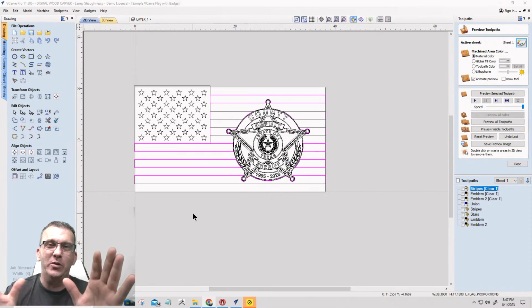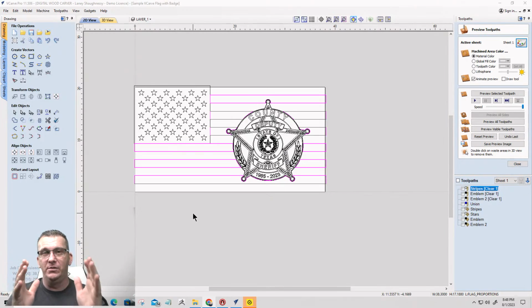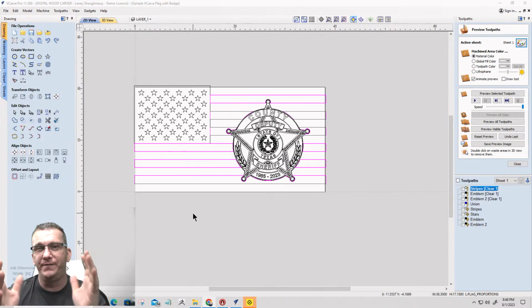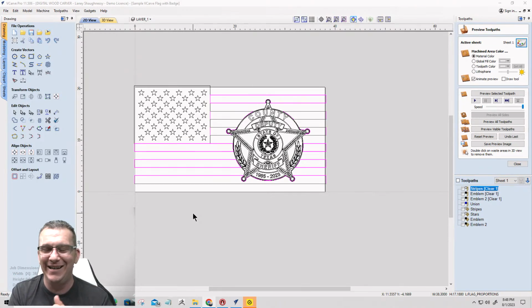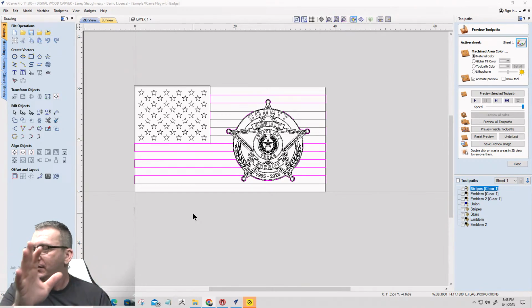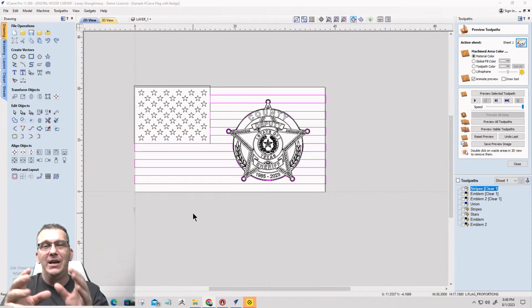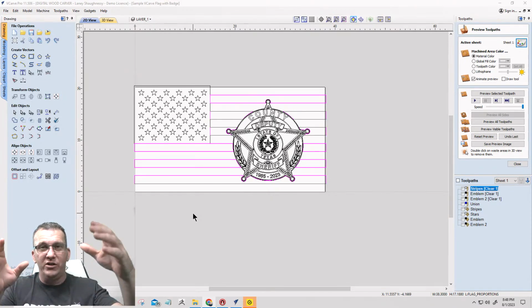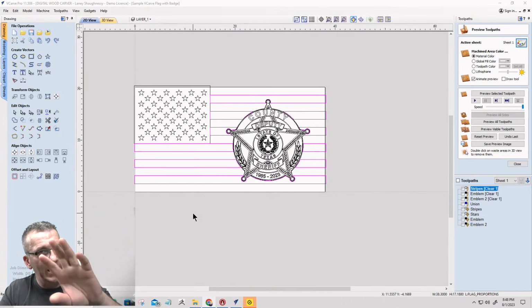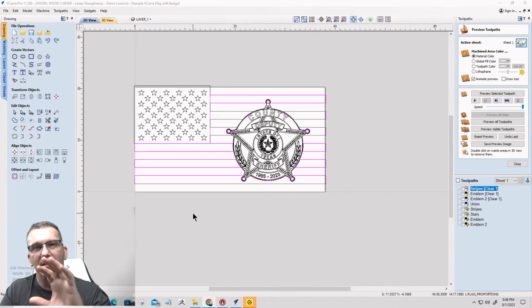Anyway, a larger bit, let's say a 2-inch diameter, we're probably going to be around 11 to 12,000 RPMs on that item. So just keep that in mind. Turn your dials between 4 and 5, and that's your starting point. Now, we talked about going larger. The larger the bit, the slower the speed.